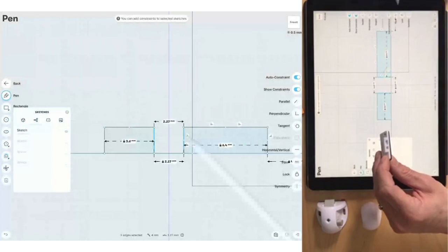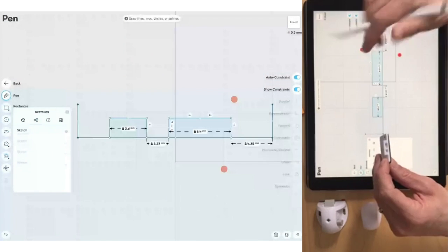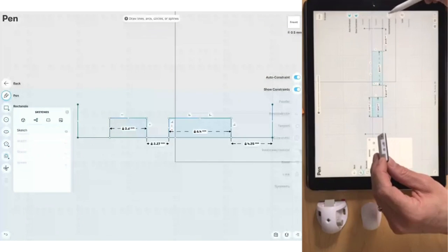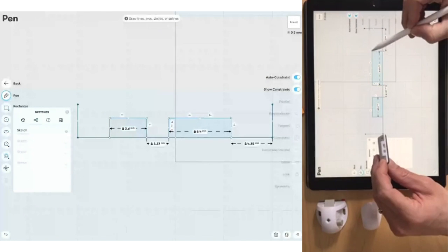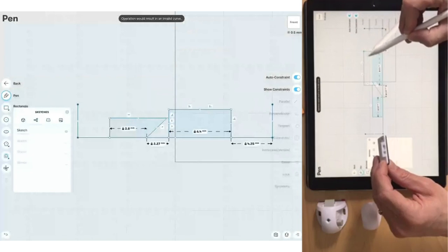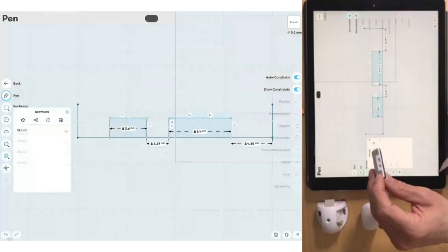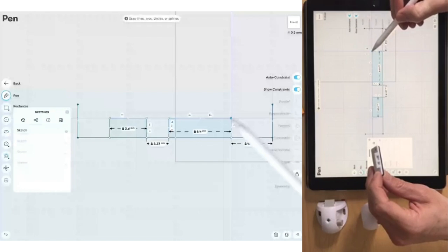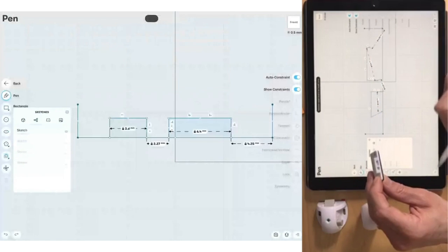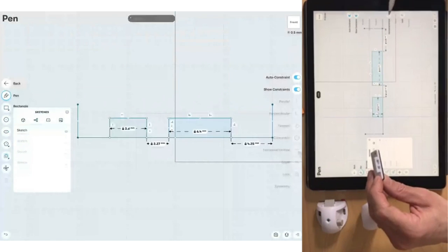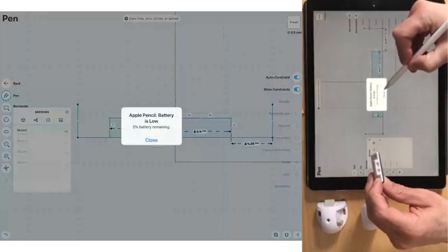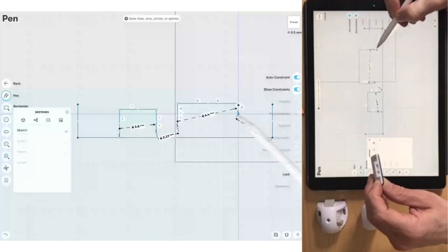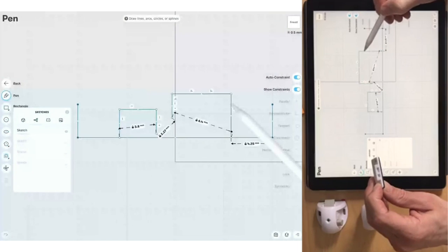These two lines, for example, I can select and say equal. I could also have selected this one and this one. Let's make sure this is horizontal. When I move this point, woo, very good that I tried this out. You see how this line was getting crazy. So let's make this one vertical. And this line needs a vertical constraint. And I bring this one to there.